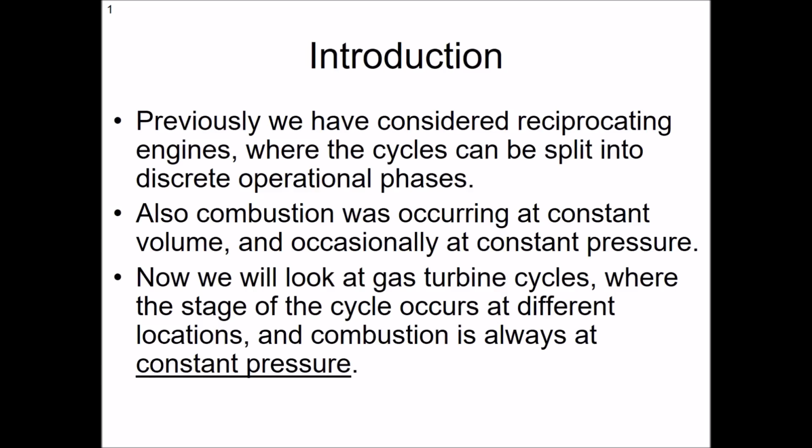That's the key thing. Now, this is something which is very much exemplified with gas turbines, because this is actually happening. Whereas with the reciprocating engines, it's very polytropic. There's things happening simultaneously because the piston is moving and changing the volume of the chamber. But with the gas turbine cycle, when heat is added, there's absolutely no change in pressure at all.